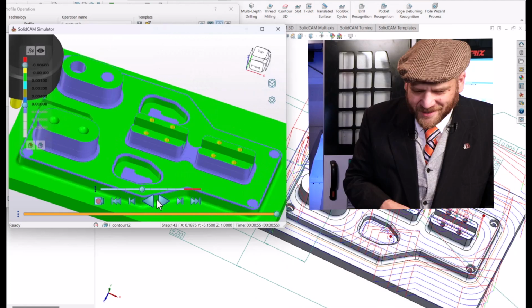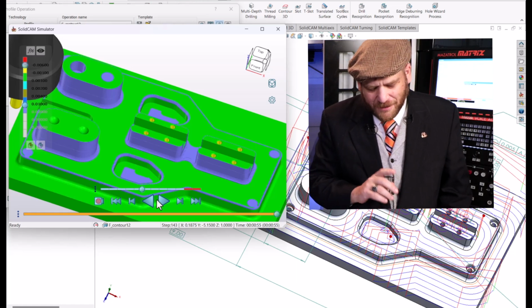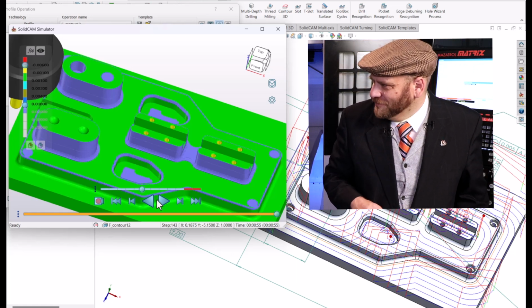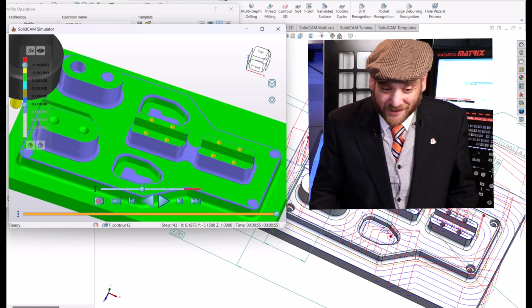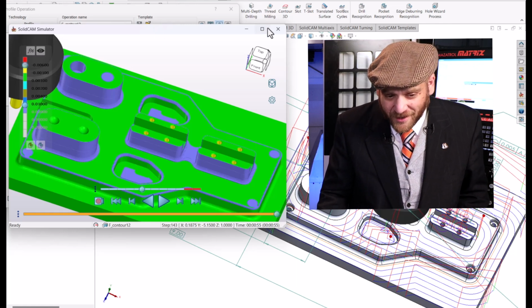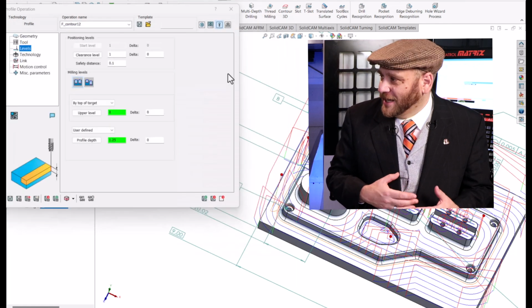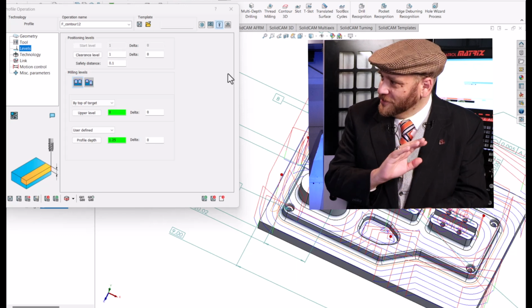And I did check, even though there's not a call out, I made sure that all those radiuses were the same. Okay. Yep. So again, because I have that model there in front of me, even though there was no MBD tied to that radius, I was able to just go in and measure the detail on the model.